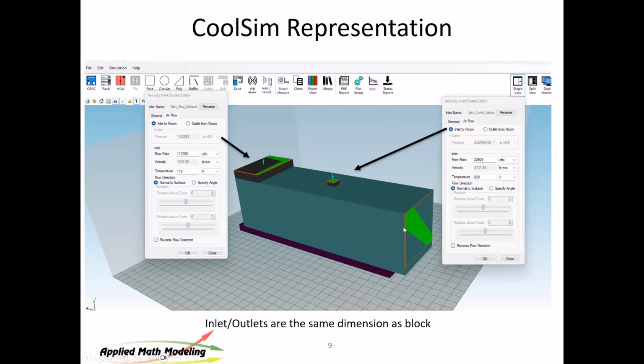You notice there's no arrow. It's pointing in because it's pulling air in. But pulling in doesn't matter quite so much as the exhaust. The exhaust coming out is hot, so about 120 degrees Fahrenheit is typical. It does depend on the design, but that's not unusual. And you see here, this one's set for 110. Again, about 110, 120,000 CFM. This one only has one outlet. Some have more than one outlet.